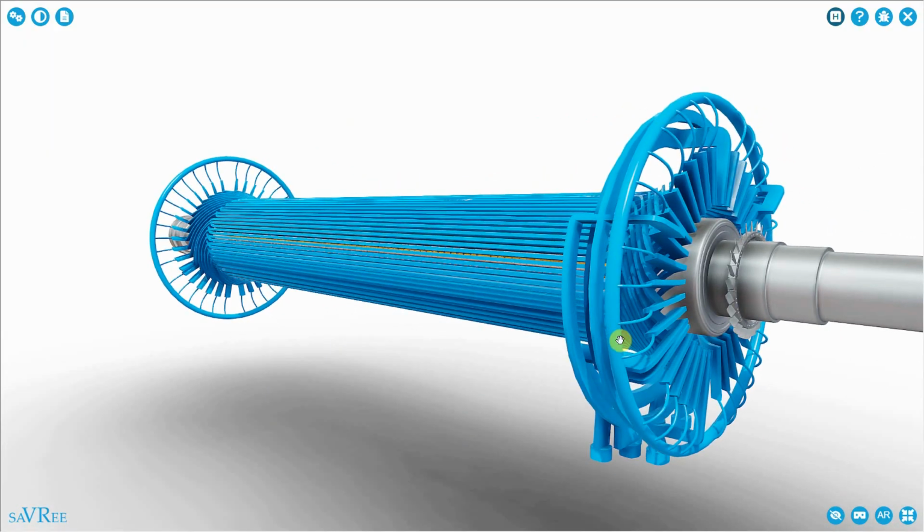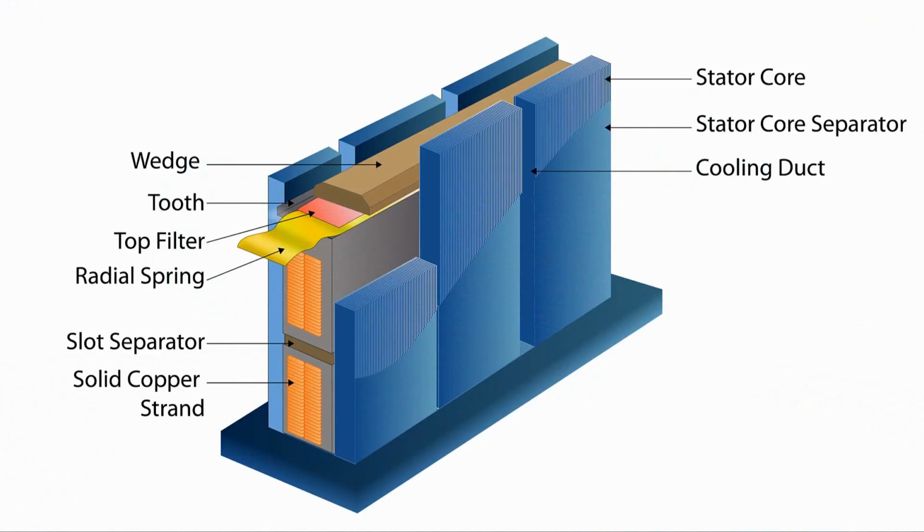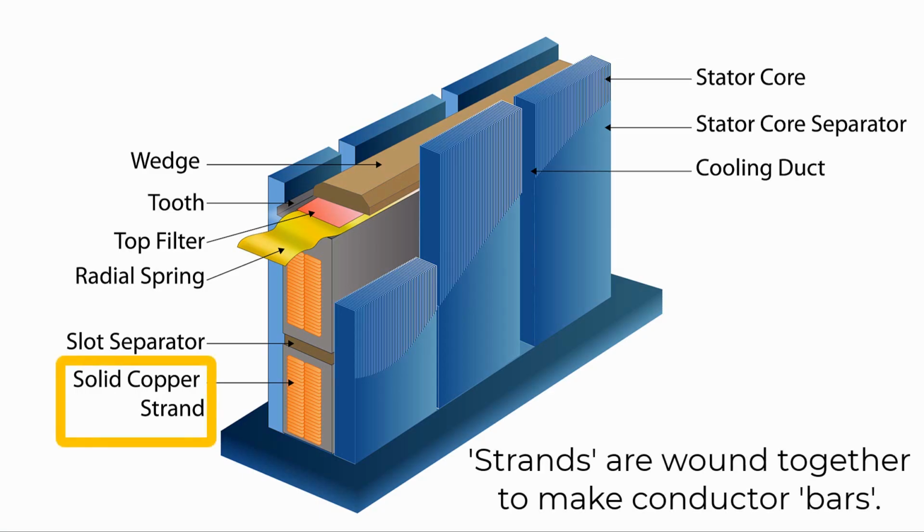The design of the stator windings and rotor windings is also not so simple. The rotor is most likely cooled by air or hydrogen. The stator, air, hydrogen or water. We don't have solid copper bars that run through our stator. There are different designs to cool our stator and rotor.